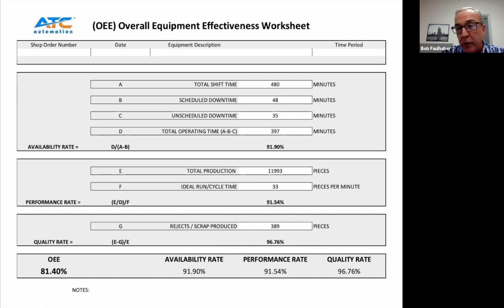The first thing we're going to do, I think this is a better way to do it. The first thing we do is we look at the overall OEE of the line, and that is the starting point for us. And so just to confirm that, that's the parts coming off the end of the line. That's right. That's the part. We're packaging them up, shipping them to another department, or shipping them to our customer. Right. That's exactly right. That's how the overall line OEE is calculated.